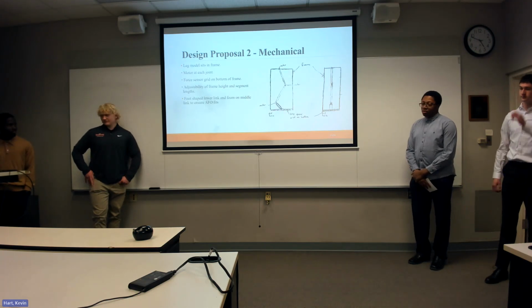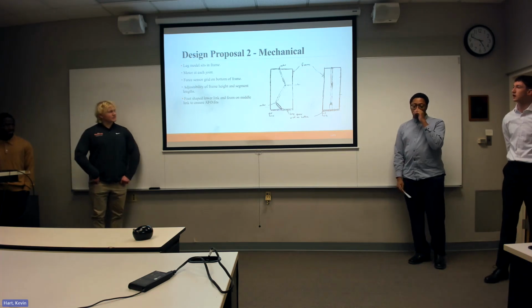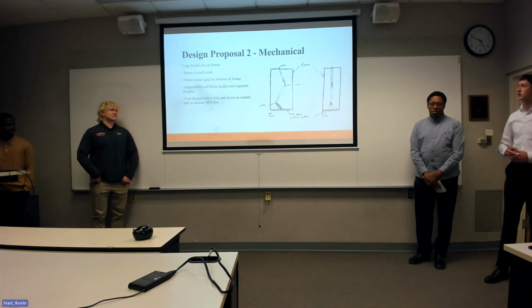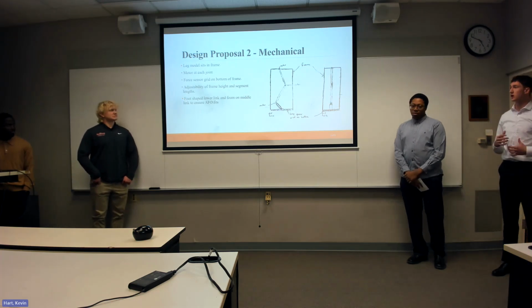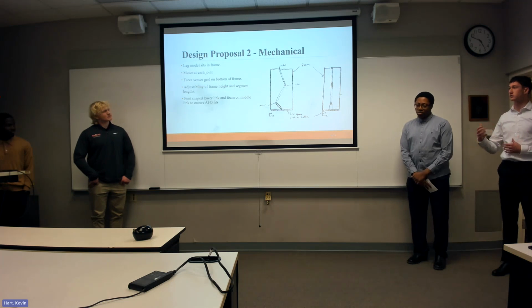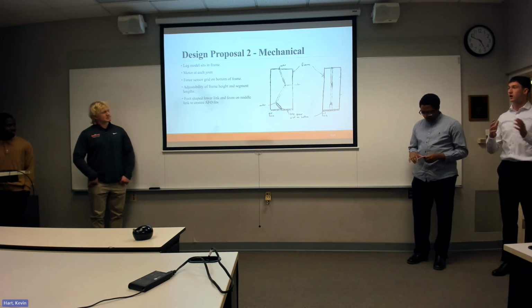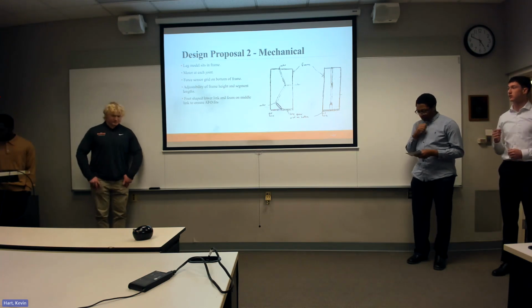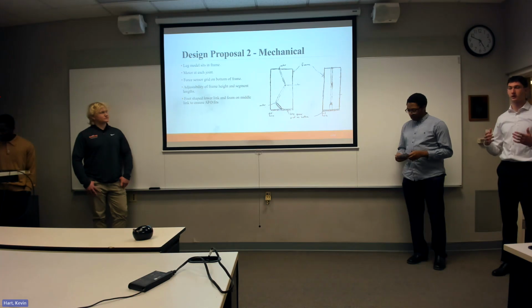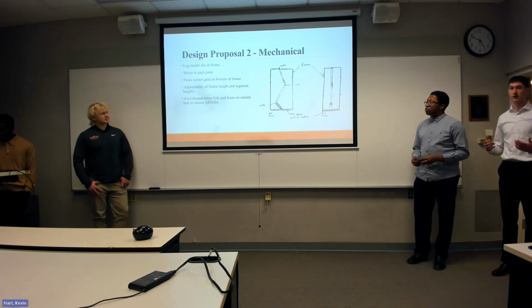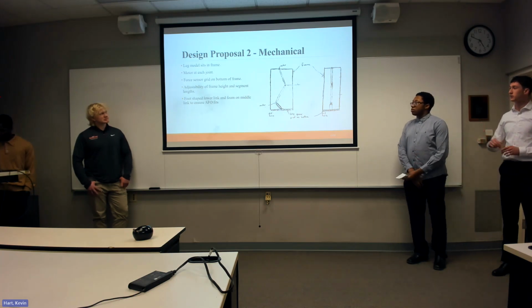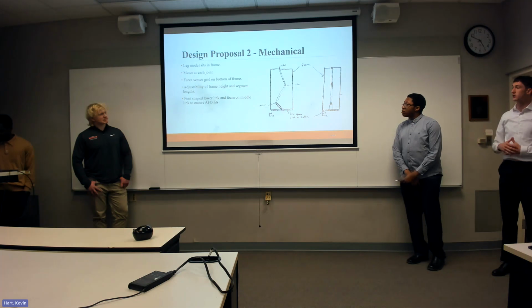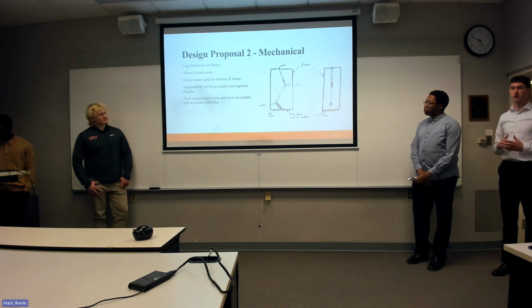So then for the second mechanical design, it's very similar to the first one. The leg would sit in this frame. The frame ensures that while the simulator is running, there's no wobble messing with the data. So this will ensure smooth motion. There would be a motor at each joint, in order to properly replicate each knee, hip, and ankle joint, and there would be a force sensor grid on the bottom in order to detect the ground reaction forces of the foot while it's walking.